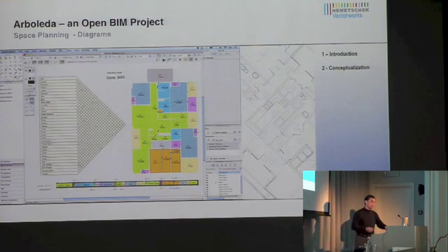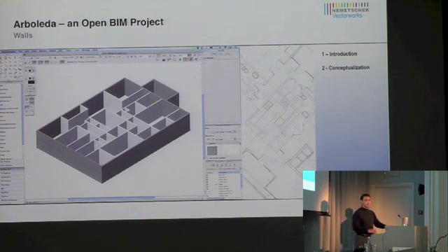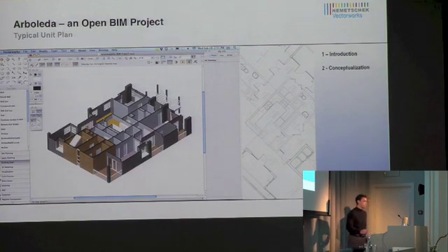Now, I show you spaces because out of spaces we created a first try for a floor plan for the apartment. So I have exterior walls and I have interior walls. And by the way, you have to remember that these objects that I'm using are not custom made. They're out of the box, just what I call the BIM objects. Walls are mainly one of them because they contain IFC information ready to go. That is our first try. That's what we saw the first time, with a little bit of work.